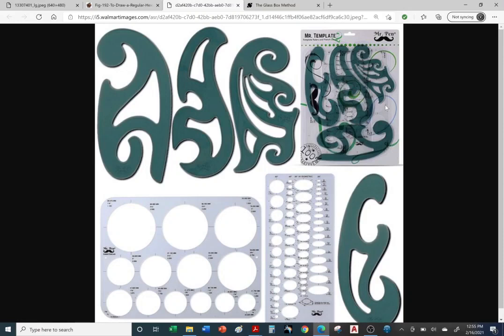Now, one thing I did forget to mention, coming back to these templates. When we were drawing using mechanical pencils, we would use these templates to draw perfect circles. We also use French curves. In some areas you need to draw some curvature, and you would use part of the French curve to accurately draw your curves and not do it by freehand. We also have templates with ellipses. Why would we use a template with ellipses? Well, this template is specifically made for isometric views, so we would use these ellipses to draw our holes.